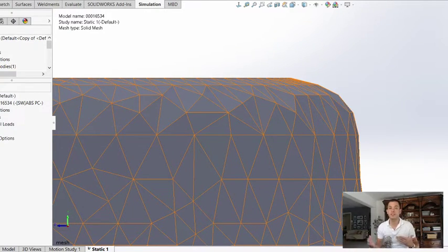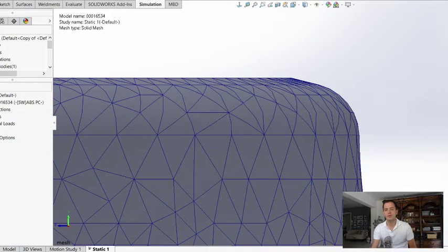That's essentially what finite element analysis is. And the more accurate representation you have of the geometry itself, the more accurate your answer is going to be. So what you can see is you are missing a pretty big amount of that geometry by cutting it off there by using a draft quality element.